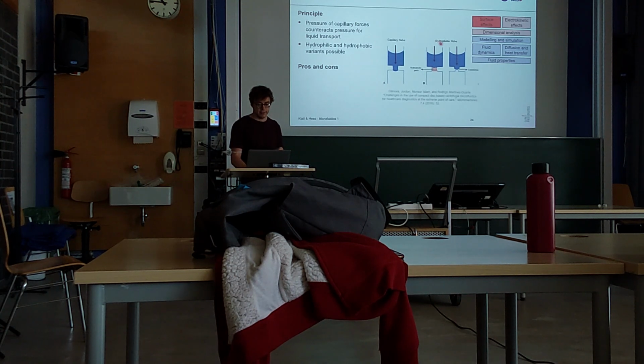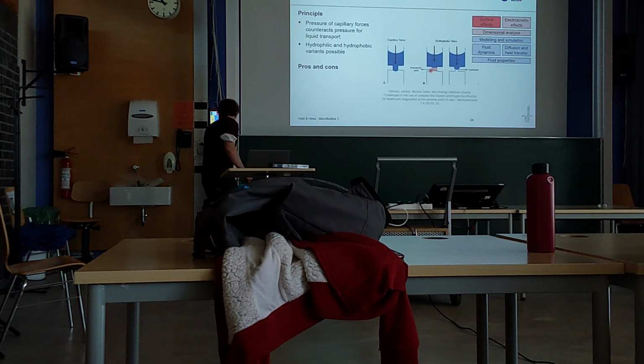I guess it's easier to imagine for the hydrophobic valve. If you have a hydrophobic patch here, for example, then you would generate a force. When the liquid moves onto this, you would have a force that pushes the liquid back into the initial direction because of the contact angles at the walls here.